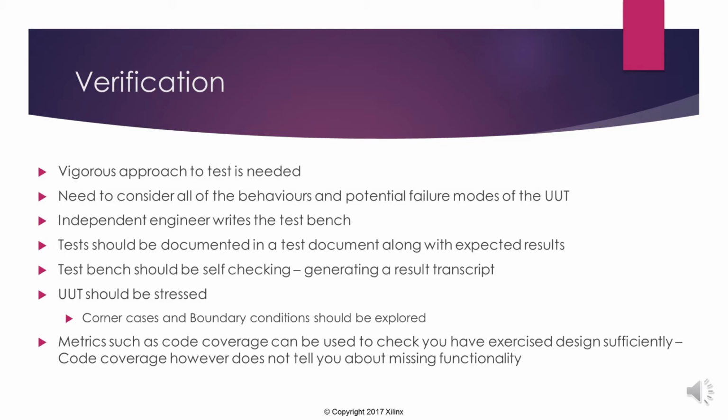Now what we should do as well is have a document that defines the test strategy that we're going to do. So if you remember back many slides ago to the requirements flow down, we had the requirements flow, the test spec, and the verification and the test spec. So we should have a test specification for each element of each module of the FPGA, saying this is what we're going to do, this is how I'm going to do it, and that should be peer reviewed and signed off as well.